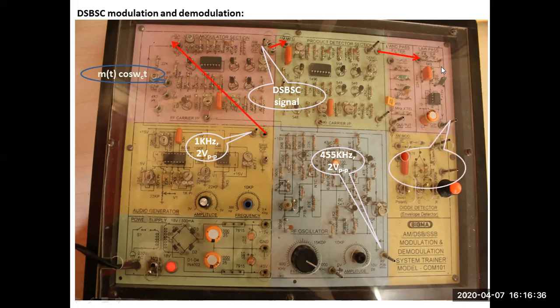At the output of low pass filter section, we will observe the recovered modulating signal. Note down the frequency of recovered modulating signal. Write down the conclusion from the observed DSBSC spectrum and recovered modulating signal frequency.